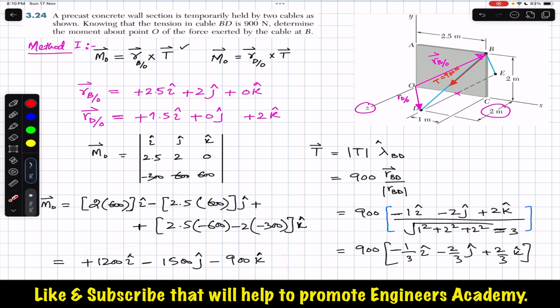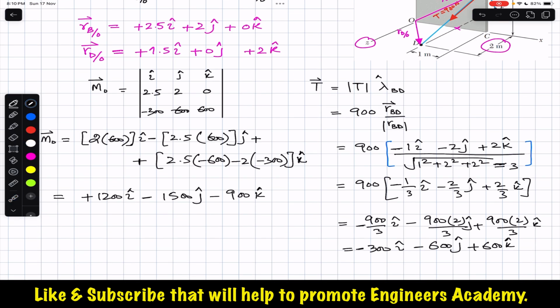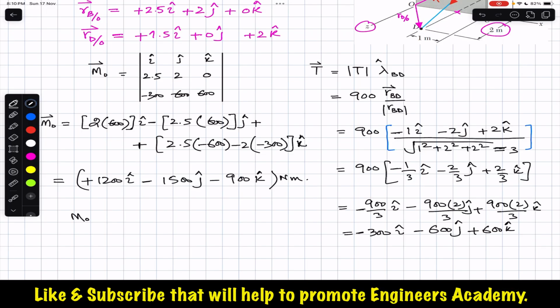The moment about point O is 1200 Newton meter in the positive x. So we will have one component of the moment in the x direction, and in the negative j direction, we have 1500 Newton meter. We will have one component in the negative j direction, and one component in the negative z direction. If we were asked to find the magnitude of the moment about point O, remember that the units are in Newton meter. We need to take the squares of all the components and then take the square root.